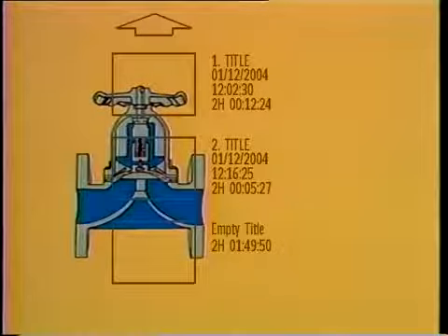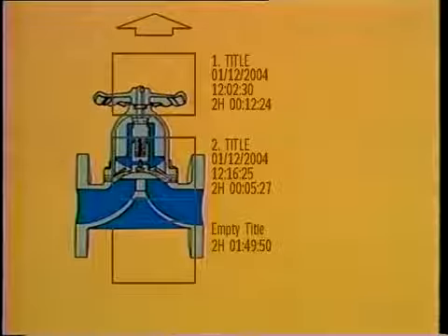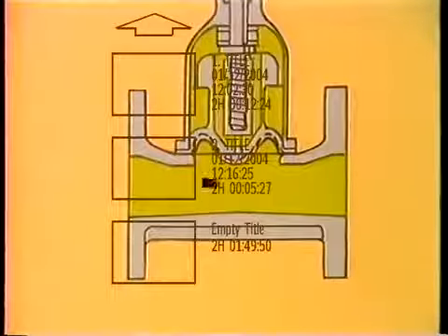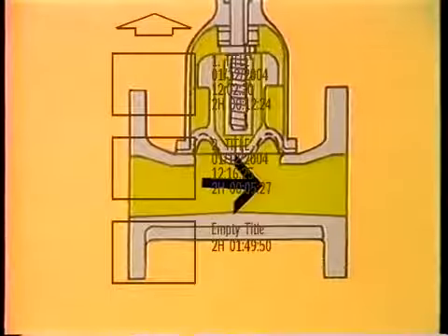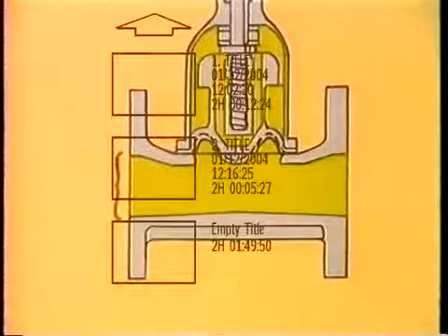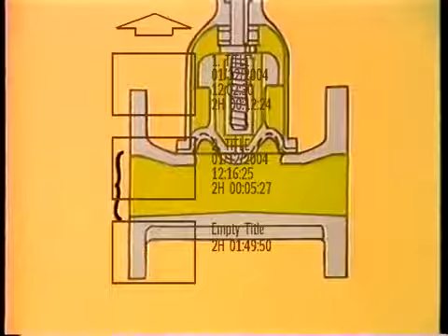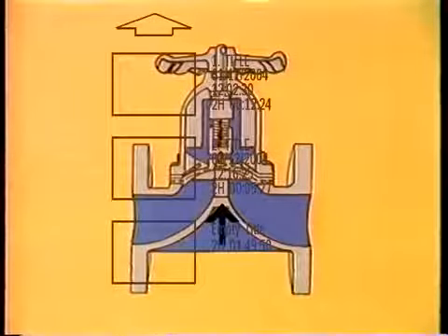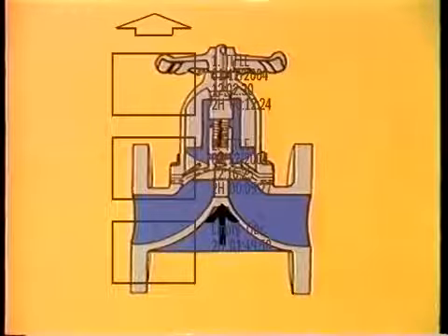There are two basic body designs used for diaphragm valves, the weir and the straight through. As the name implies, the straight through body has no obstructions where the diaphragm seats. The bore of the valve is the same as that of the piping it's attached to. The weir, on the other hand, has a raised surface where the diaphragm seats on the valve body. This allows for the use of stiffer diaphragm material, but reduces the area of flow through the valve. You'll find additional information about material used in the manufacture of diaphragm valves in your text.